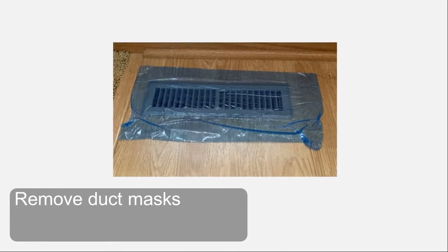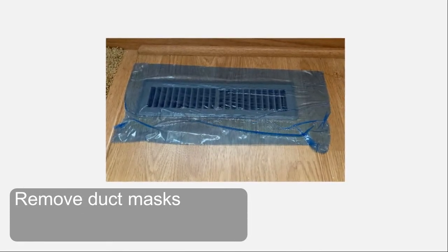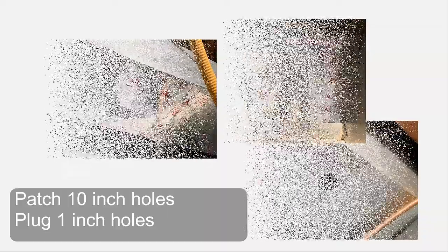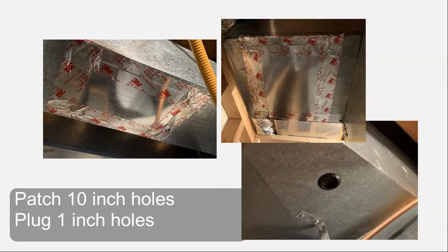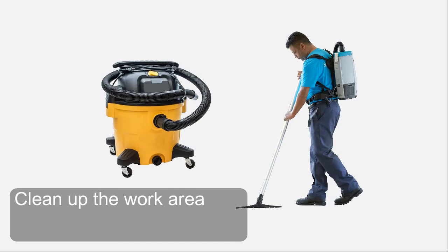Clean up your work area. Use a backpack vacuum or a shop vac to clean up. Load your tools and equipment. Patch 10-inch holes, plug 1-inch holes. Replace the filter. Clean up work area.